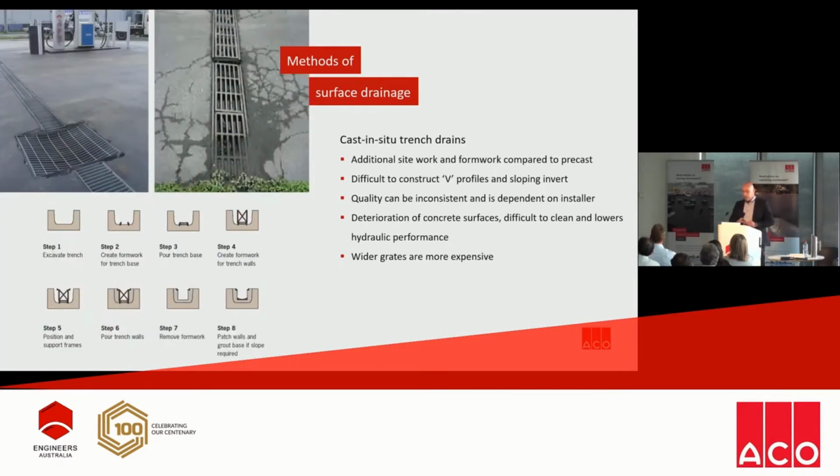Some of the other methods available on the market are cast in situ trench drains. Some of the things to consider with cast in situ trench drains: they do require additional site work and formwork compared to that of a precast unit. It can be difficult to construct V-shaped profiles and sloping inverts in a cast in situ environment. Quality can be inconsistent. It's dependent on the installer who's installing a grate and frame in a cast in situ application. Therefore, because of that, you can have some deterioration of the concrete surfaces adjacent to the frame, and it can be difficult to clean and lower its hydraulic performance.